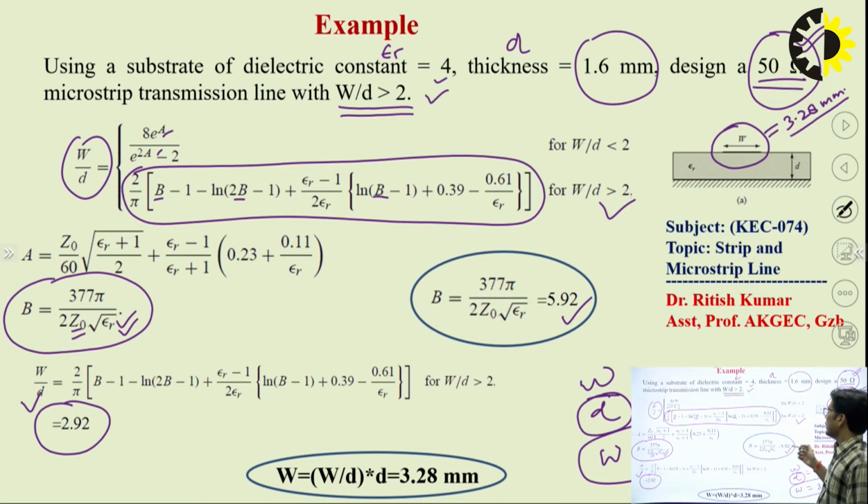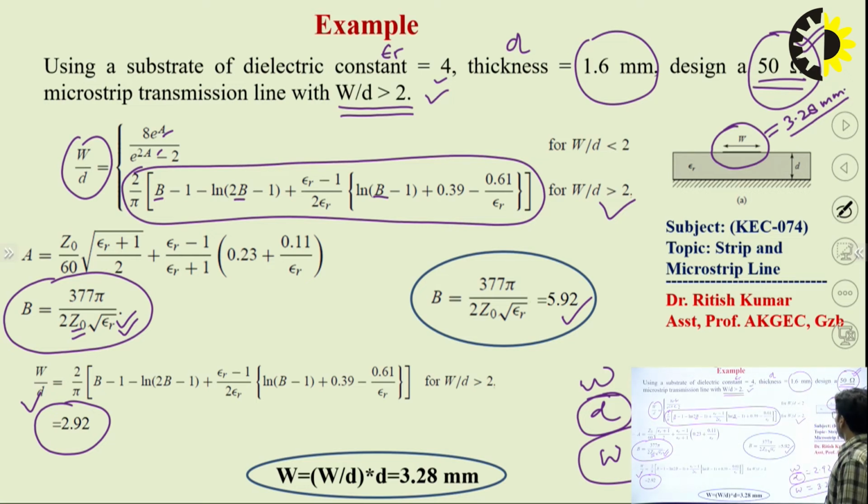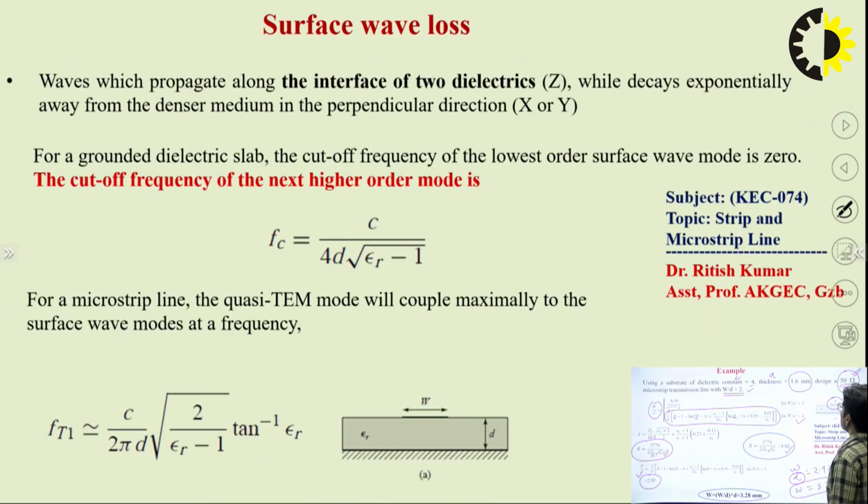So if you take the 50 ohm transmission line, there won't be a mismatching between my connector and transmission line. Most of the connectors in the commercial market are 50 ohm, so to have less reflections through the strip line we need to design a 50 ohm microstrip line. This is the main point that we need to highlight here.